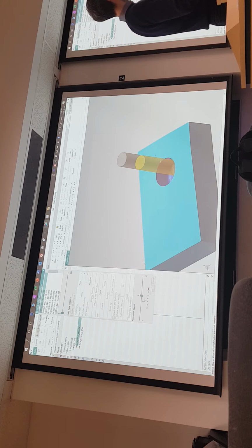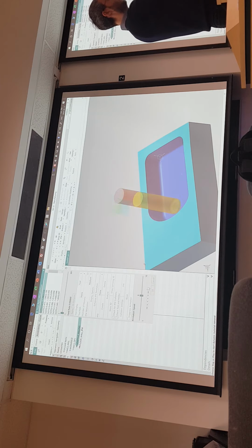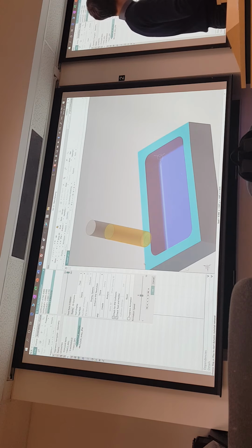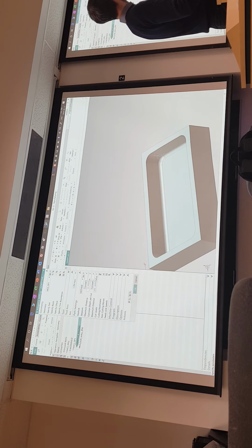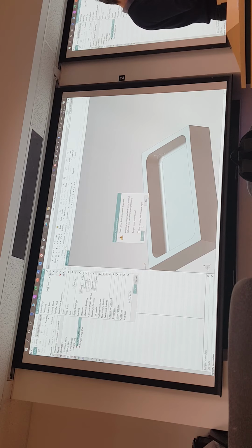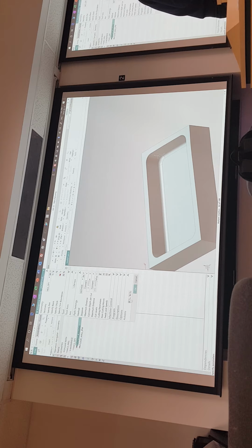So this is how it gets into the material. And then it automatically does this. You don't have to tell it. So the biggest possible part, and then it starts treating each area individually. And now let's say instead of 60, we say 1/4 inch. See, now it's a much bigger radial step over.